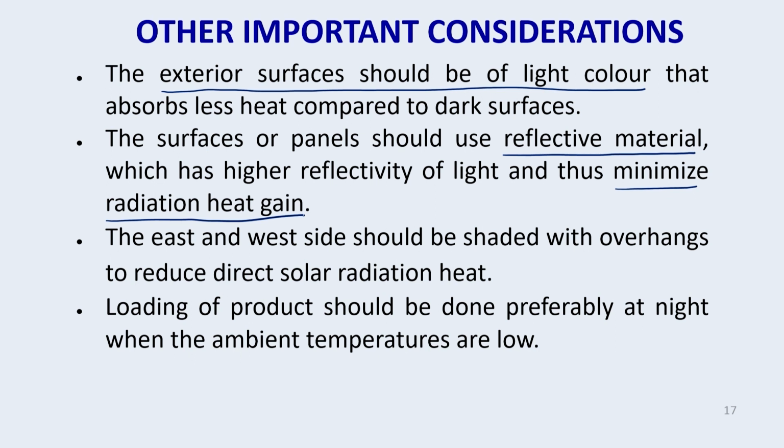If you don't have these, suppose you are having a dark color or you are not using a reflecting material of high reflectivity, what will happen? It will add to the heat load, and obviously the capacity of the refrigeration system will increase. The east and west sides should be shaded with overhangs to reduce direct solar radiation heat.